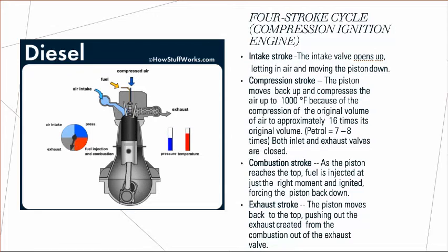A four-stroke diesel engine resembles a gasoline engine as it works on the four-stroke cycle, that is admission, which is the intake stroke, compression stroke, power stroke, and also exhaust stroke. When the piston goes down on the air admission stroke, the lower pressure in the cylinder allows a charge of air into the cylinder through the inlet valve, which opens just before top dead center. Once the piston has passed the bottom dead center and is beginning to ascend, the inlet valve closes and the upward movement of the piston compresses the air charge in the cylinder, causing a quick rise of temperature.